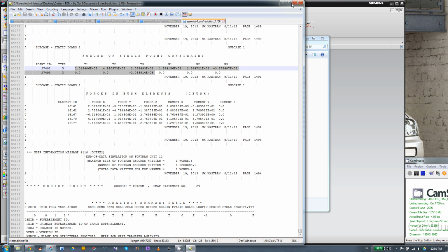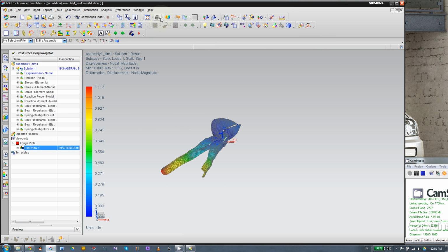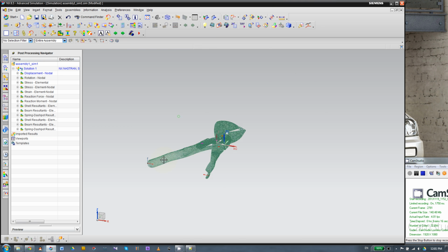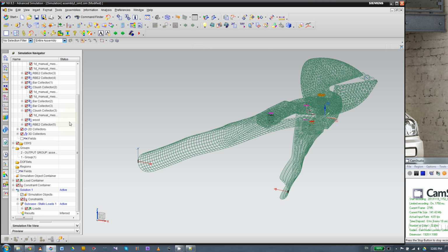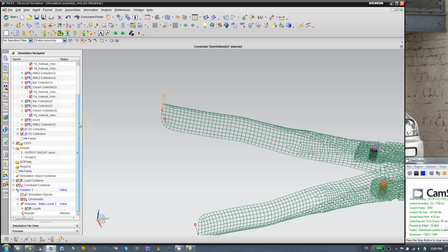All right, and now let's demonstrate what will happen if we don't have the constraint here. And if you know what will happen, you can stop right now. And this is what Dr. Zada did in the class. It's just for telling you that we need this constraint. If it's not there, this cutter will rotate like this with respect to the wood, and that will be your rotating axis. Okay, so let's kill this first.